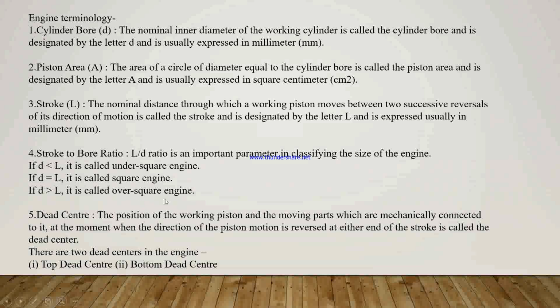Okay, next is the dead center. Dead center is the position of the working piston and the moving parts which are mechanically connected to it, at which the direction of the piston motion is reversed at either end of the stroke. There are two dead centers, top dead center and bottom dead center.